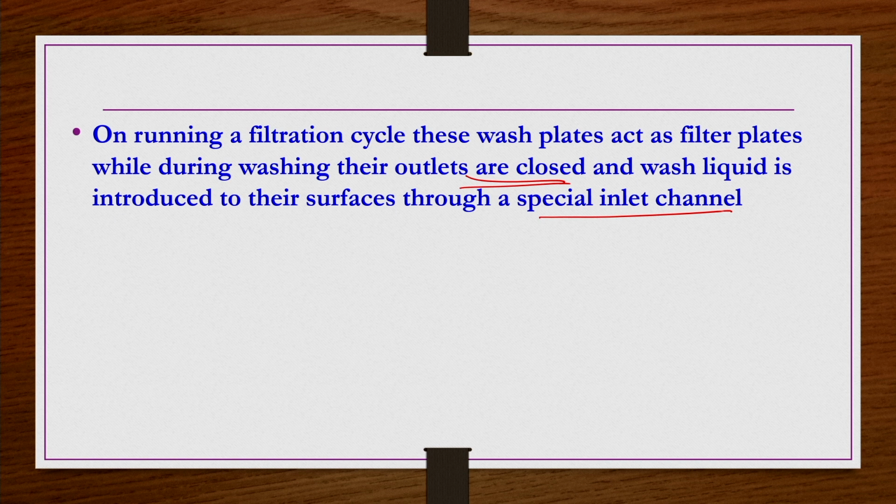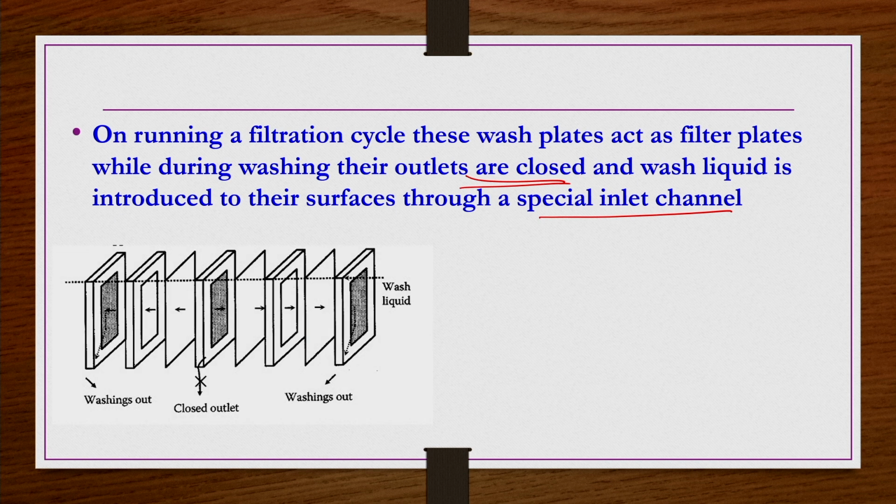The holes provided at the top in both the plates and frames, as I have shown, are going to act as channels that one can use as the special inlet channels for the wash liquids. So, now here wash liquid. The same arrangement, the same stack we had previously for the filtration, is there for the washing also, because indeed in that same unit the cake has been deposited that we are washing. So there is a frame, there is a medium, there is a filter plate, there is a wash plate. Okay.